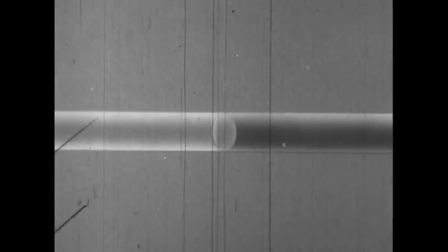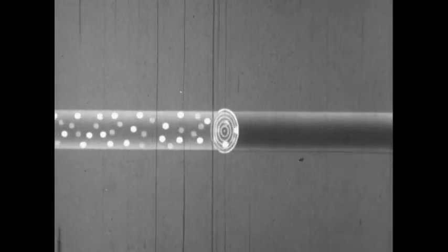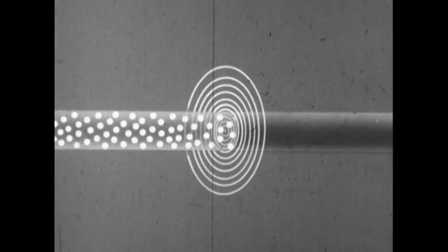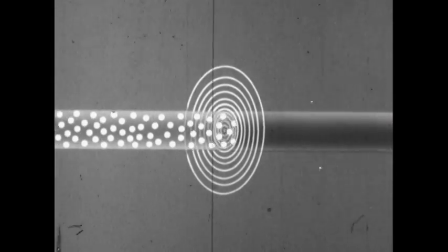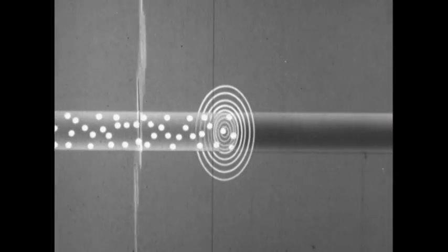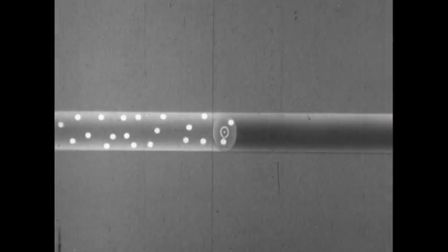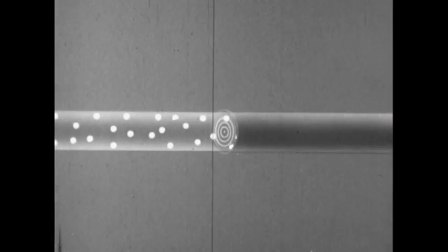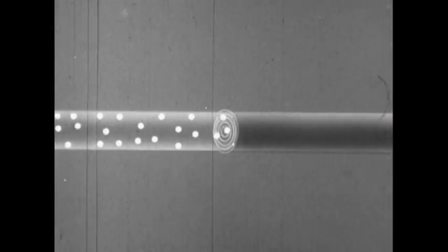As the current builds up, lines of force cut through the wire, expand outward, and build a magnetic field. When current reaches maximum and drops off, the field collapses, again cutting through the wire, until both current and field pass through zero at the same instant. When the current reverses, the field again expands and collapses. This cutting of the wire by the field is the basis of inductance.